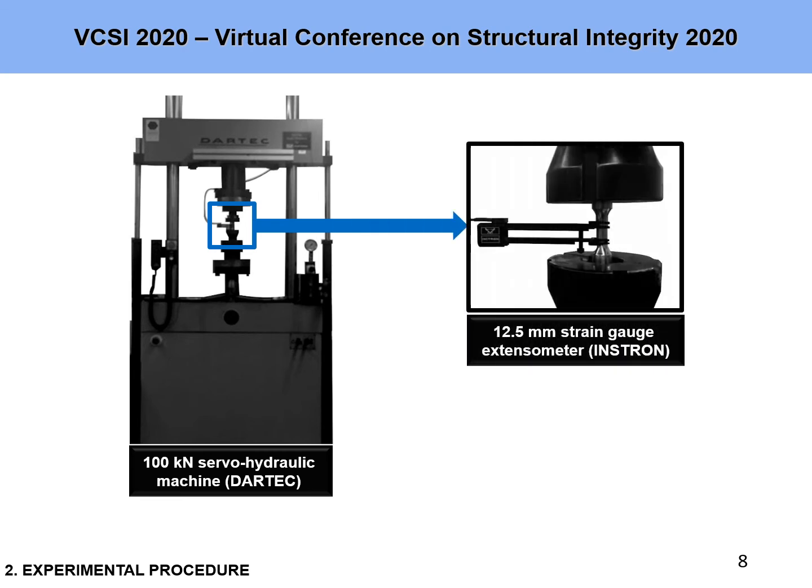The testing machine used in the study was a Dartec with a load cell of 100 kN combined with a 12.5 mm strain gauge extensometer from Instron.